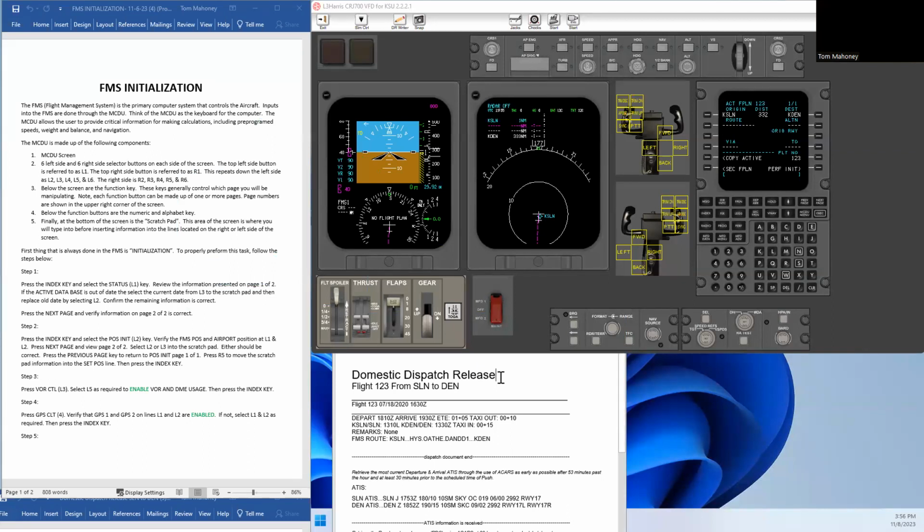So the first officer leaves the gate agent, walks out onto the ramp or down the jetway, takes a look at the nose number, verifies that the nose number matches what the nose number is on the release. We're just going to pretend that it does. Going to walk into the cockpit, look around, make sure everything is correct, make sure that we have our maintenance logbook, make sure that the circuit breakers are all in, and verify that we're actually on the correct airplane by looking at the aircraft number that's probably placarded somewhere up on the forward panel.